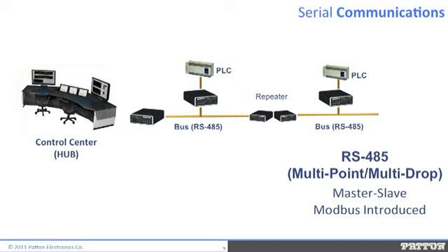Half-duplex communication can occur between any two devices. How is this done? When a device is not transmitting, the transmitter is in a high impedance or off state, as if the transmitter were not connected to the circuit. During these times, the receiver is on and may receive a message from another device. Each device has a name or address. Only when the message bears its name will it take the appropriate action to the message.